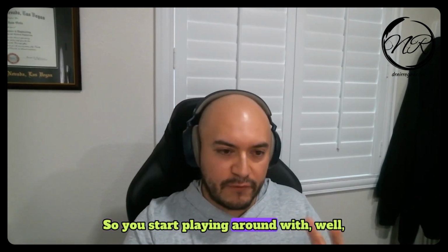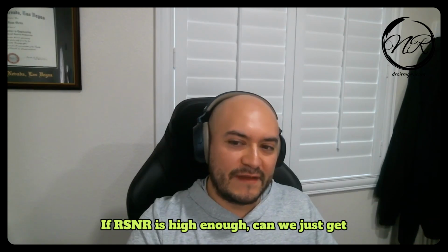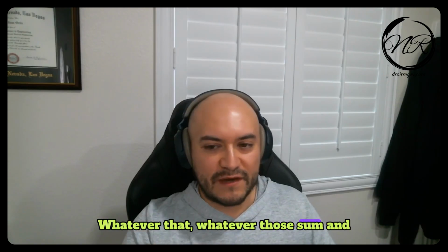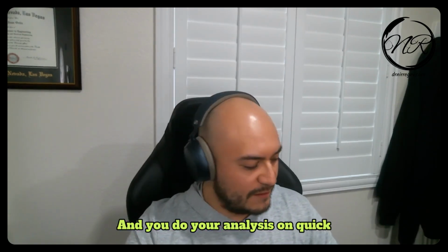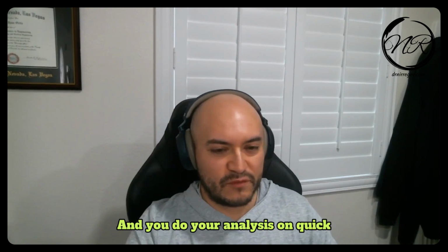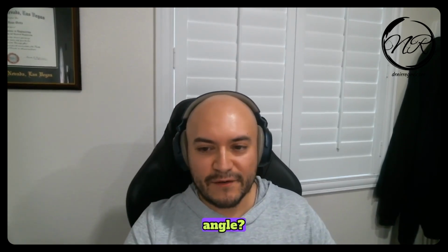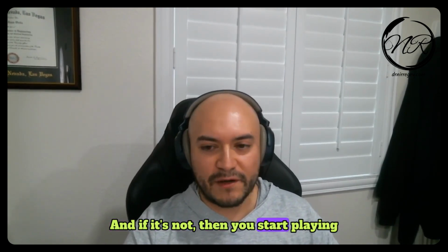So you start playing around with, well, if our SNR is high enough, can we just get away with splitting the array in half evenly? Whatever those sum and differences look like, is that good enough? And you do your analysis on a quick simulation. Hey, I have this target moving. How close can I get to the angle? And you're like, hey, this is good enough. Let's keep going. And if it's not, then you start playing around with other stuff.